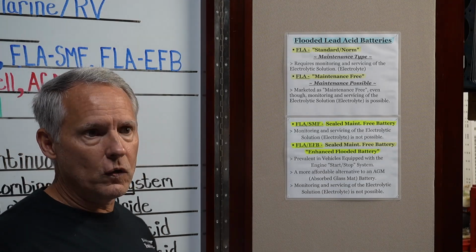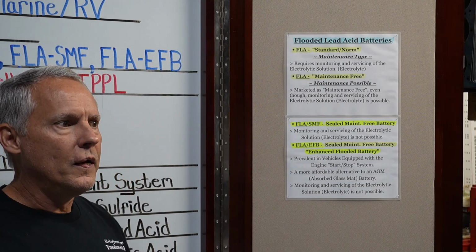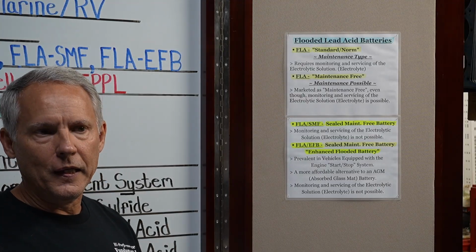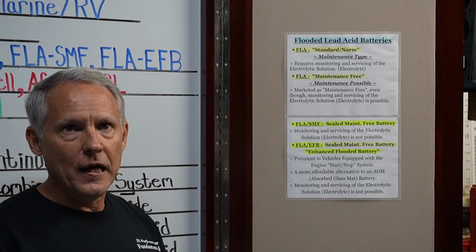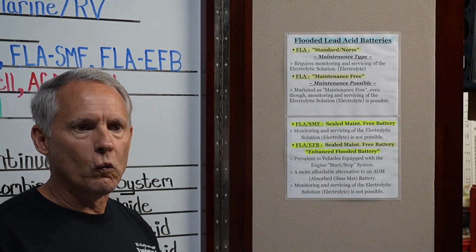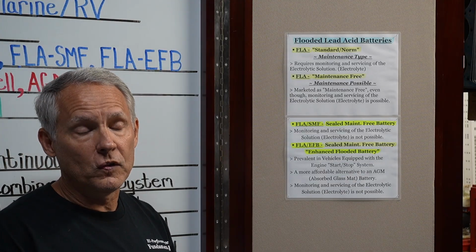If it was my own vehicle and the battery was out of warranty and I thought it was necessary, I would open it up and get in there and I would service the electrolyte. It wouldn't bother me a bit. Knowing that if I did that while the battery was still under warranty, I might void that warranty. So something to take into consideration.